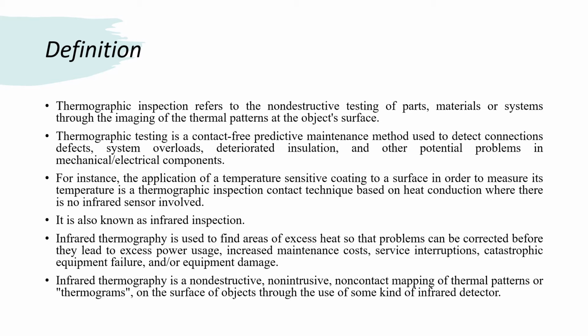But thermographic testing is totally a contact-free predictive maintenance method. It is specially used for detecting loose connections, system overloads, deteriorated insulation, and other potential problems in mechanical or electrical components.